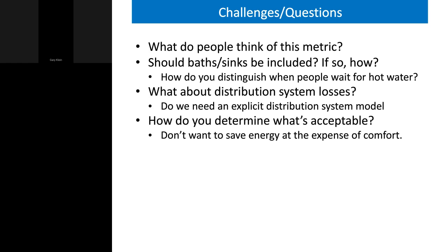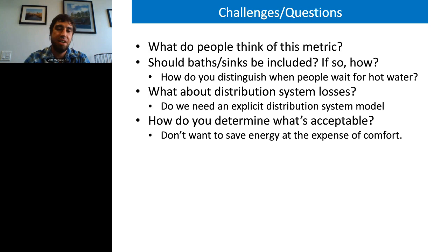This is from Brennan Mangino, I think. During your example simulation, what volume, heat pump capacity, and electric resistance element size did you use? So it was a 50-gallon heat pump water heater. The element was 4.5 kW, and the heat pump size, I think the nominal was around 970 watts as output. It's based on a real manufacturer's equipment. It's a model that we developed based on lab data from a product that's actually out there.